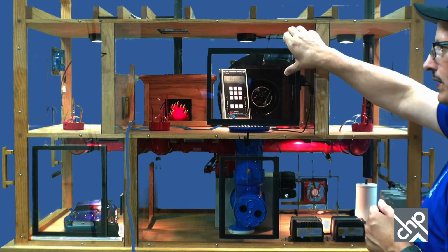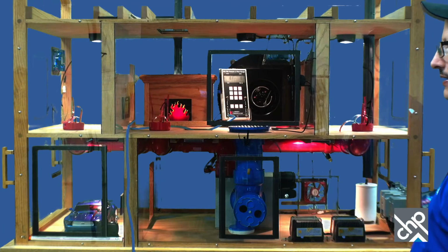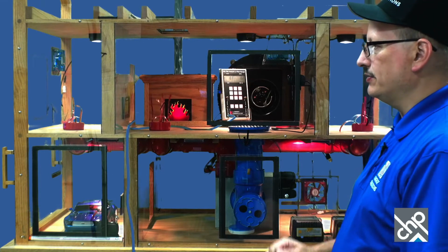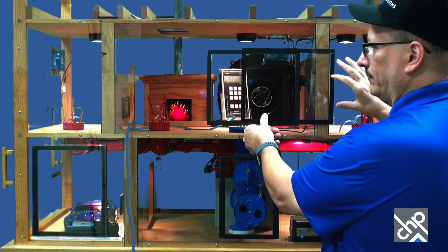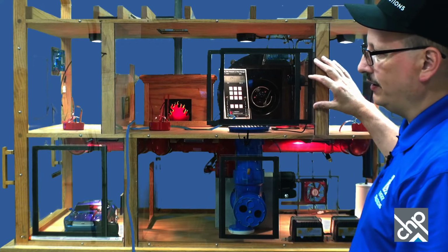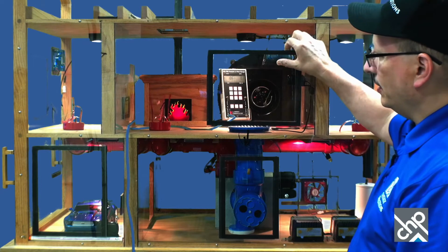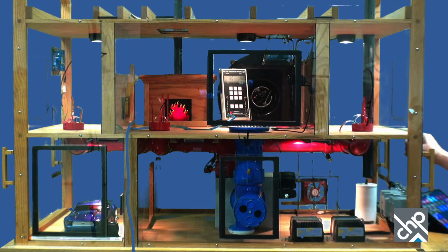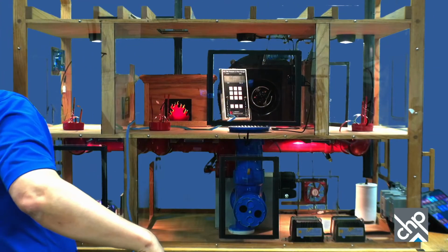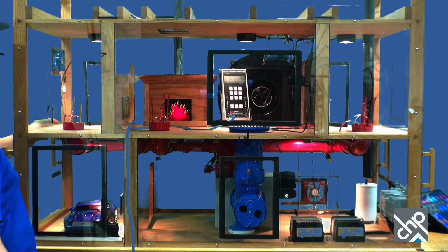Now, if I open up the window, what happens to that? You can watch that -4, and as I open that, you see the pressure goes back close to 0 now, and now the smoke goes out the chimney. And again, as we tighten the house up, you start to see this get a little more affected there. And as I close it all the way, it gets even more negative. Now, if I open the doors back, if I open that door and open this door, it works fine. I'm closing back.